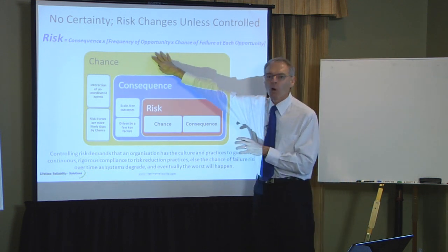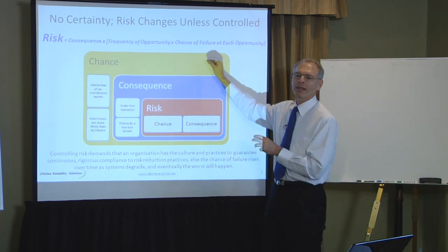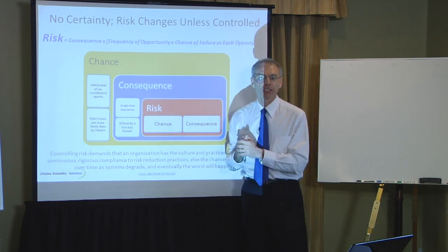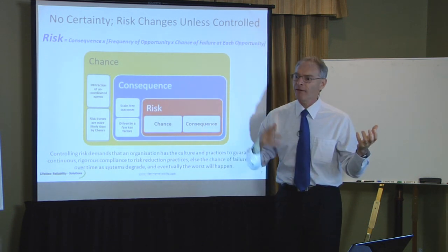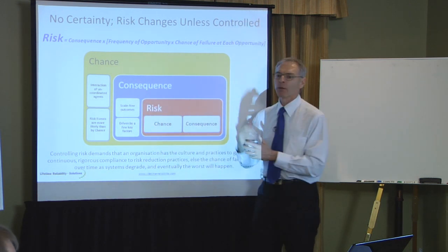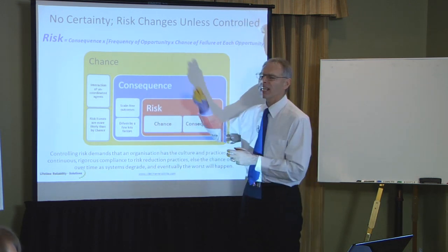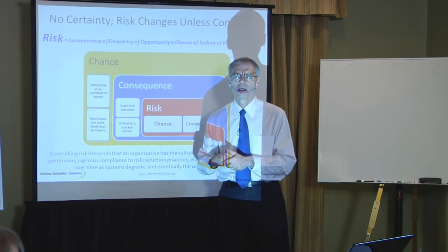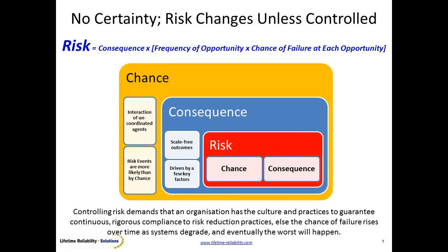The opportunity's always there. The fact the particle has not yet got into the bearing, that's a chance issue. So I can have dirty oil and have the machine never fail because the chance never occurs. But the point is, with lots of dirty oil, the opportunity is always there for it to go wrong. And of course, with enough time and enough situational circumstances, the risk eventually comes our way.